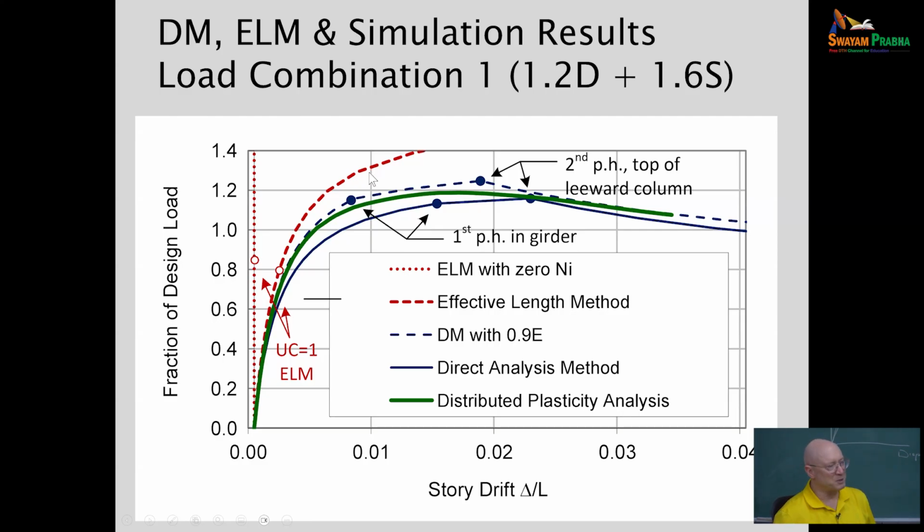Now, again, what is 0.002 coming from? Again, in the Americas, at least in the U.S., Canada's different. Canada's very different in many ways. The notional load, or that equivalent imperfection, is tied to the Code of Standard Practice, and well, the largest out-of-plumbness that would be allowed before you might get hauled to court by the owner to fix it is basically 1 in 500. Okay, so that's that. But again, nominal stiffness.